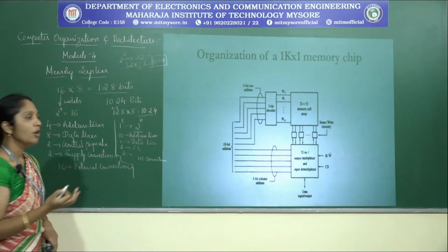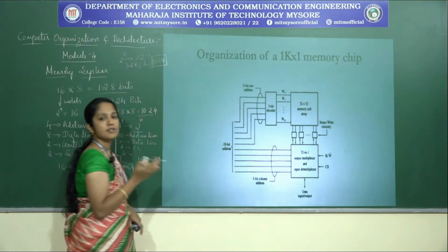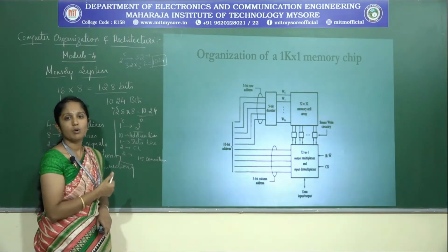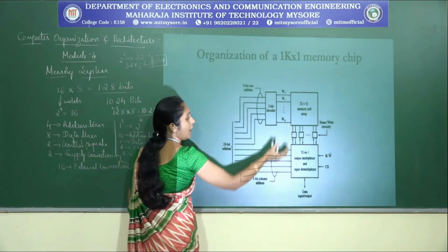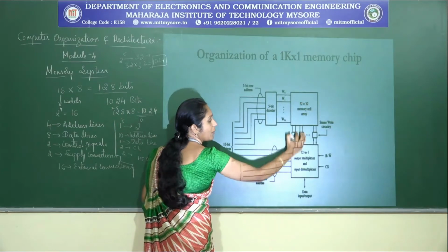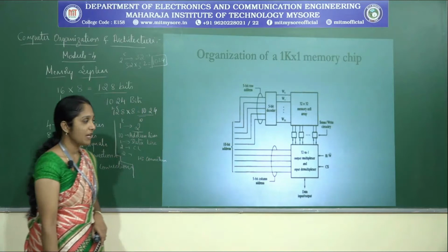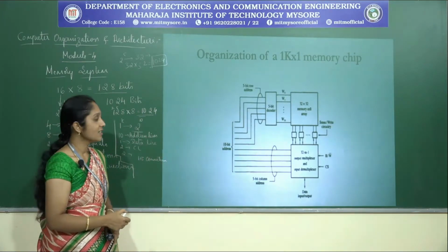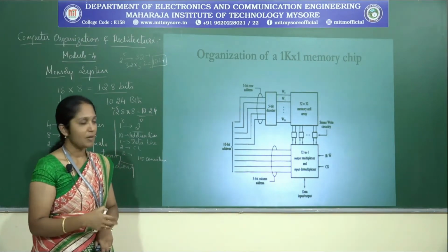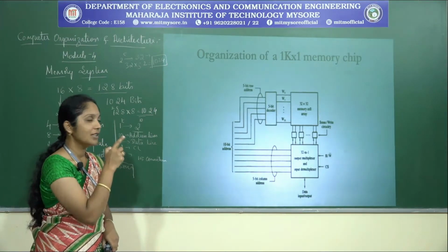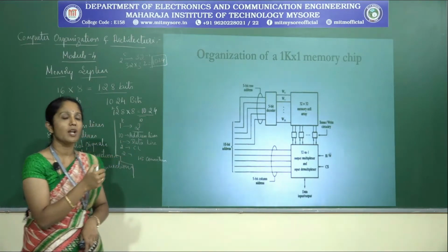We make two groups of the address line such that one of the 32 rows is selected, and those row bits are given as input to the output multiplexer and the input demultiplexer. It is a 32 to 1 output multiplexer and an input demultiplexer.